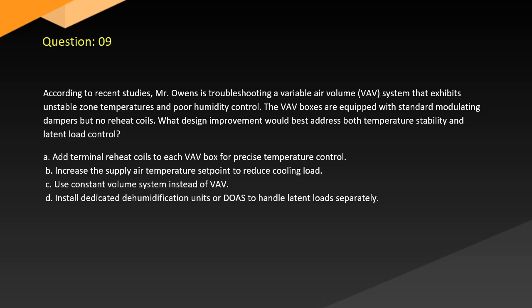B. Increase the supply air temperature set point to reduce cooling load. C. Use constant volume system instead of valve. D. Install dedicated dehumidification units or DOAs to handle latent loads separately.